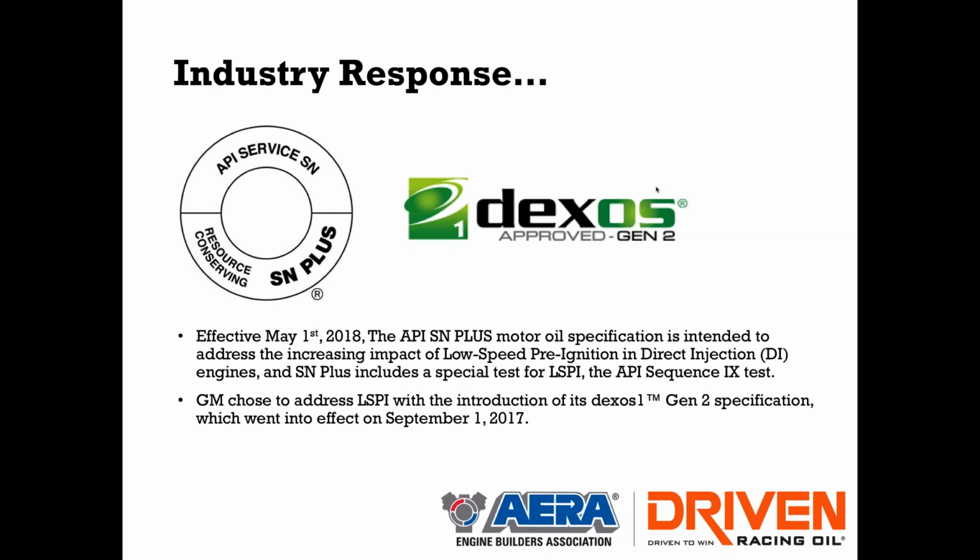The GM Dexos Gen 2, and you'll see that if it has that Gen 2 under the Dexos, then that is also an updated oil that has a reduced or modified detergent package to pass GM's proprietary LSPI test as well. And if the oil's got both of those, then you're really good. You're covered on the LSPI side.